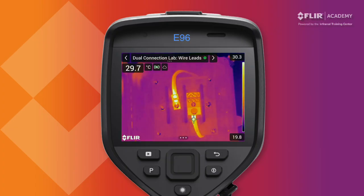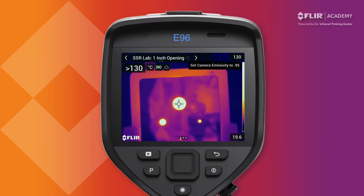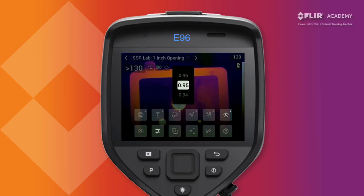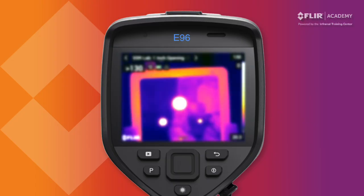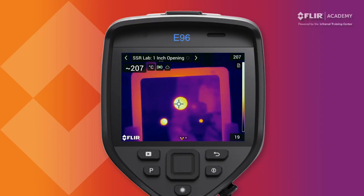Next is the dual connection lab in the Infrared Training Center classroom, where another image is captured and the status condition is set to OK. With the spot size ratio lab target, the inspection note instructs the thermographer to use an emissivity of 0.95. Additionally, we can also see that the temperature of the target has exceeded the current range setting on the thermal imager. After changing the range and allowing the camera to stabilize, we can now measure the temperature and set the status condition to OK.